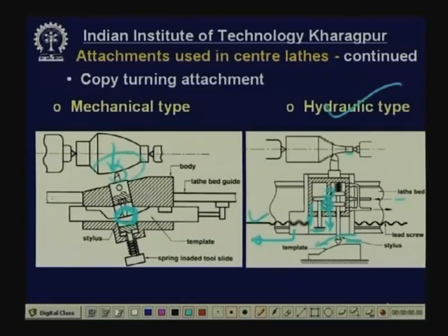Now, when this cylinder along with the cutting tool moves downward, along with the slight downward movement, say delta y of the tool, this cylinder also gradually moves downward delta y. First of all, this port was opened because of the movement of the stylus. After the stylus moves, because of the pressure oil coming into this chamber, the cylinder will come down.